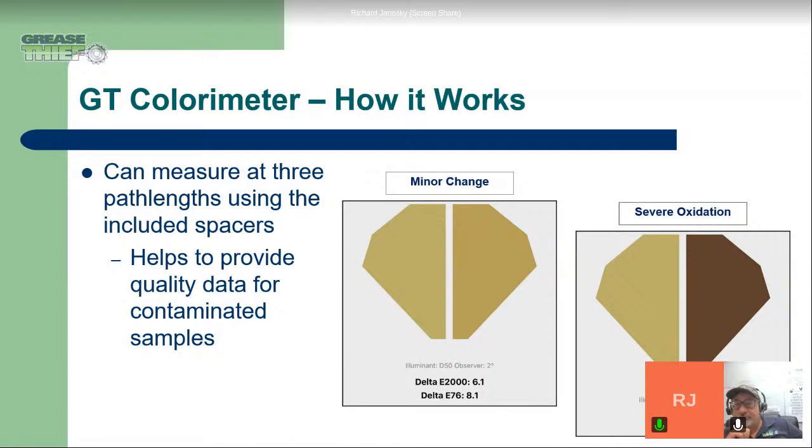It's what happens over time, but the grease is being taken care of through maintenance practices, and you can continue to use it. Yeah, and certainly if a customer, an owner of robots, can avoid having to shut down to do a grease change out, that keeps that robot in business, and that's where the return on investment is. Keeping it reliable, minimizing the downtime, getting as much of the life out of the grease as you can, and only changing it out when it has to.